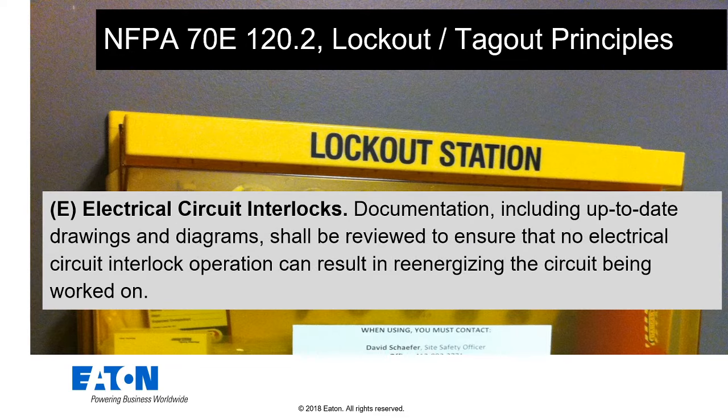So documentation, so in the electrical circuit interlocks, documentation including up-to-date drawings and diagrams shall be reviewed to ensure that no electrical circuit interlock operation can result in re-energizing the circuit being worked on.